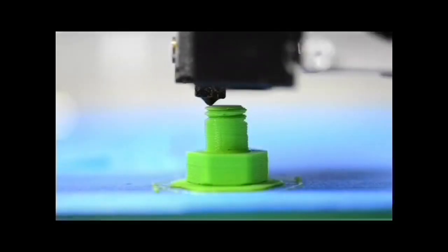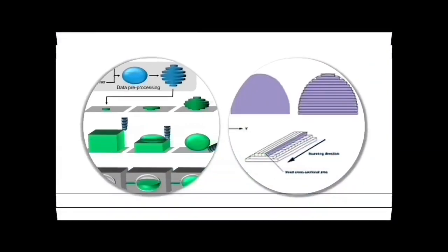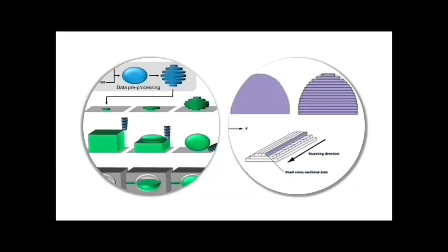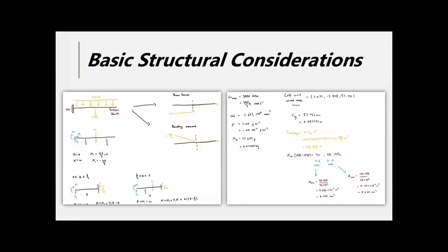The blades and nose cone of our turbine were created as one piece via a rapid prototyping machine that placed down hot fused wires of ABS plastic. Because the plastic is fibrous, it has a higher strength in the direction of the fibre in comparison to the transverse direction, which has an approximately 0.2 reduction factor in strength. This means that the optimum strength of the blade centrifugally would be when the fibres are aligned parallel to the blade, which was something that we couldn't achieve given the size constraints and printing direction of the box that we were manufacturing it in.